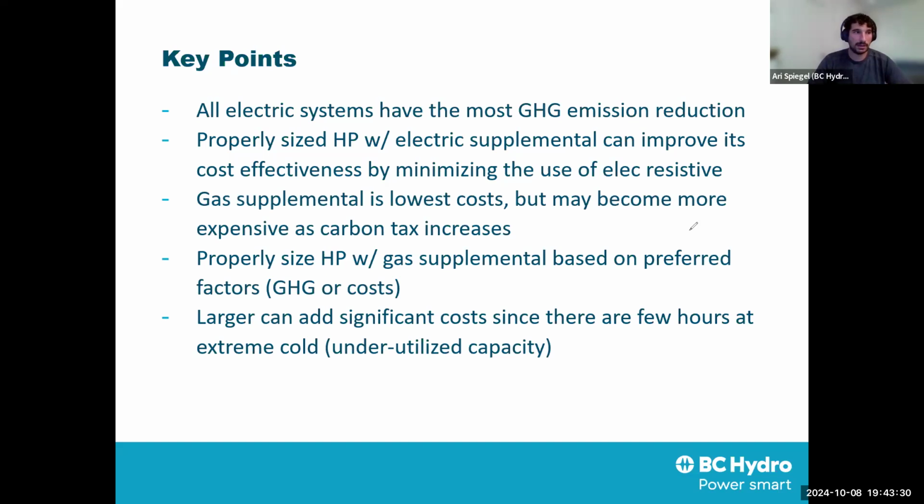Are you just looking to add air conditioning to your existing system? Are you motivated by the environment and greenhouse gas emission reductions? All those need to be considered to optimize for what's best for your situation. Larger heat pumps can add a significant cost since there's just few hours at those extreme colds, so it's underutilized capacity. So just another thing to consider in terms of that design.